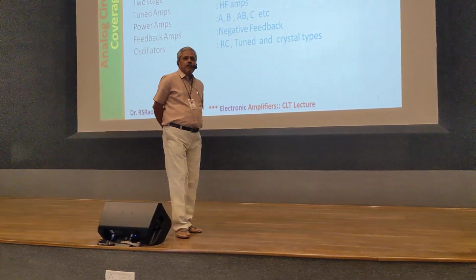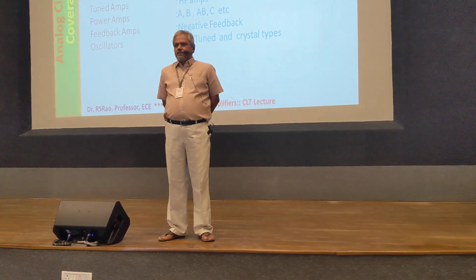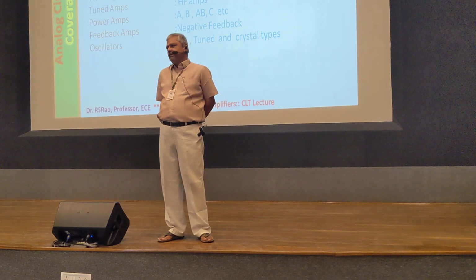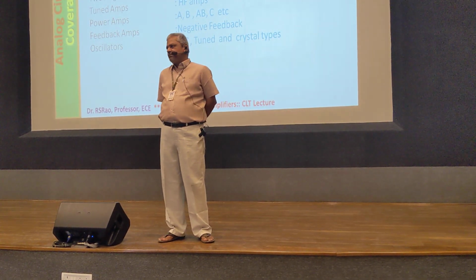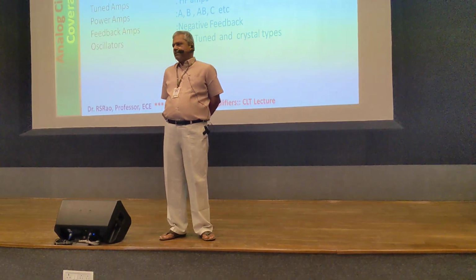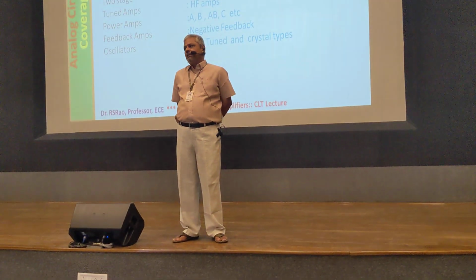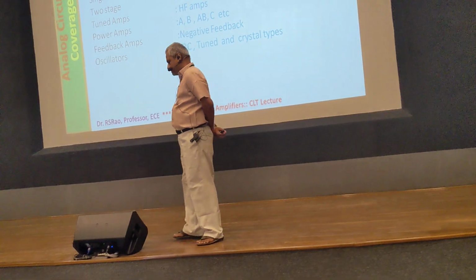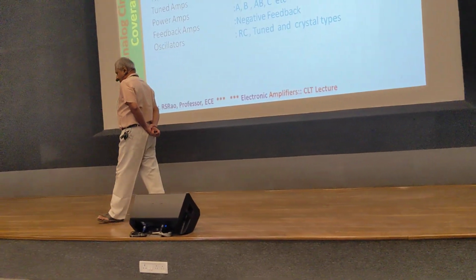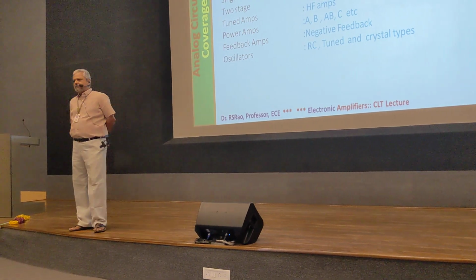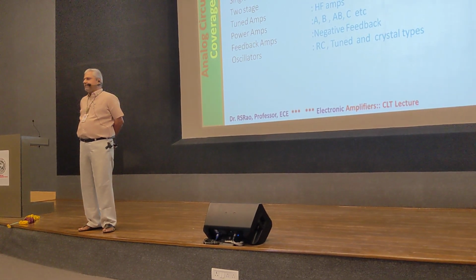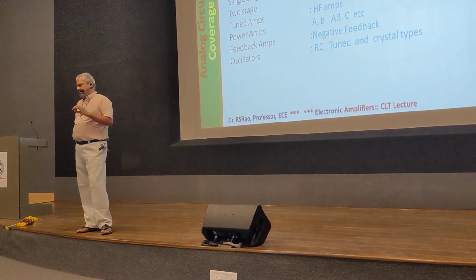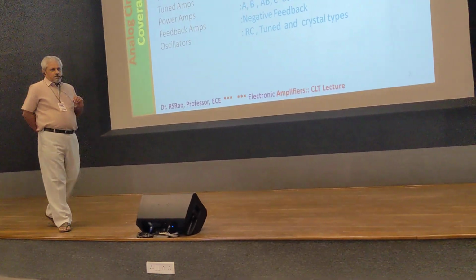That solution is if you add another CC stage to a CC amplifier, it results in a CC pair, and this CC pair is able to give enhanced input impedance, thereby reducing the loading effect on the sources. So basically the CC Darlington pair has come into being to enhance the input impedance of BJTs.